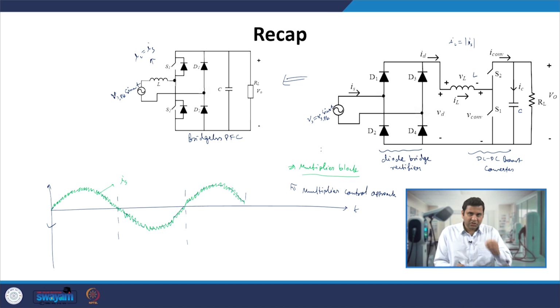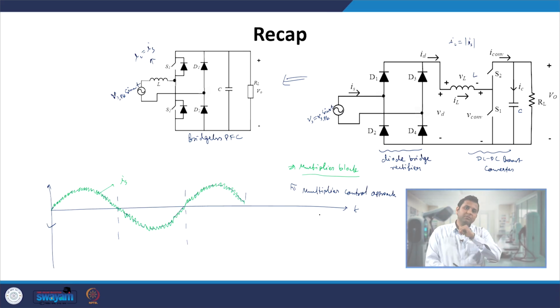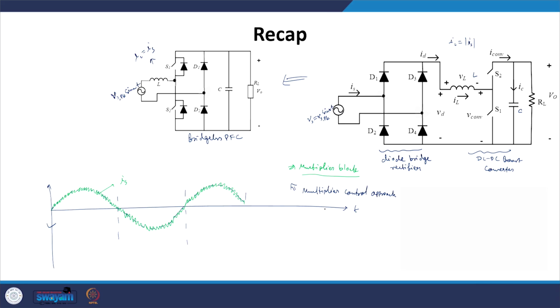That means sensing the actual voltage signal, and from the actual grid voltage you have to generate the unit sine, either unit sine omega t or modulus of unit sine omega t, or sine signal, and then multiply it with the output of the voltage controller block. So doing those things is very complicated, requires computation, and requires a high performance microcontroller.